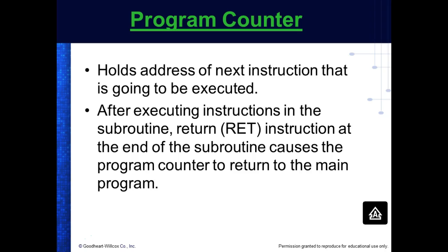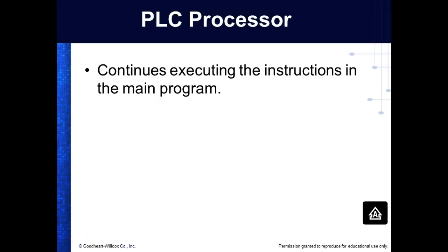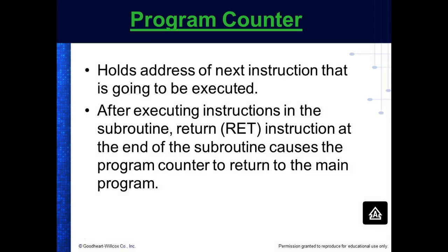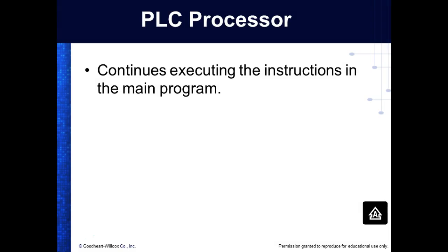And we call it pushing. The instructions in machine language are a push and a pop. If we want to manually get information off the stack, we pop it. If we want to push information on it, we push it. Or when you do a jump subroutine, it automatically pushes and pops it. It's what we call a LIFO stack. What does it stand for? Last in, first out. Push instructions on top of the stack, and pop them off. For some reason they didn't say pull, the term came out to pop.